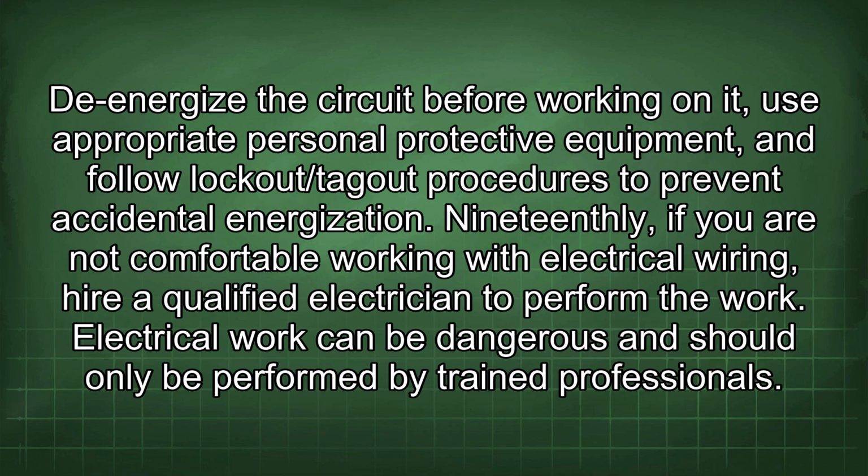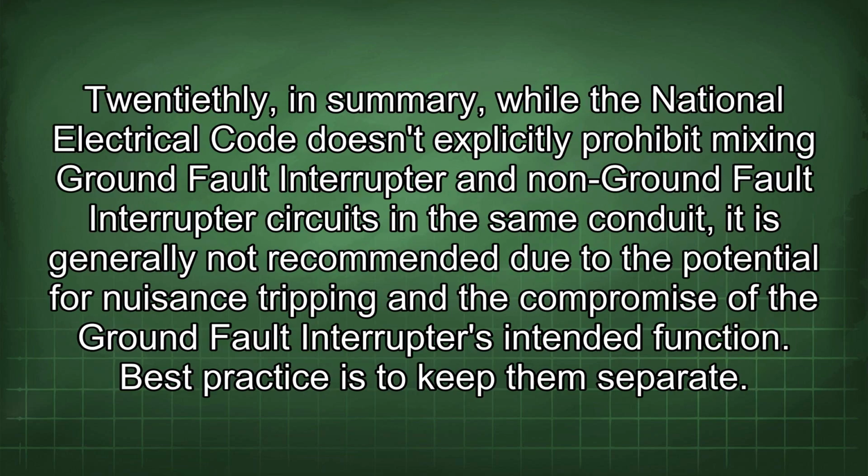19th, if you are not comfortable working with electrical wiring, hire a qualified electrician to perform the work. Electrical work can be dangerous and should only be performed by trained professionals. 20th, in summary, while the National Electrical Code doesn't explicitly prohibit mixing ground fault interrupter and non-ground fault interrupter circuits in the same conduit, it is generally not recommended due to the potential for nuisance tripping and the compromise of the ground fault interrupter's intended function. Best practice is to keep them separate.